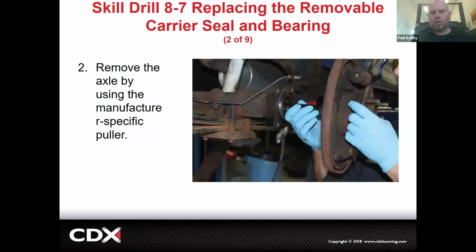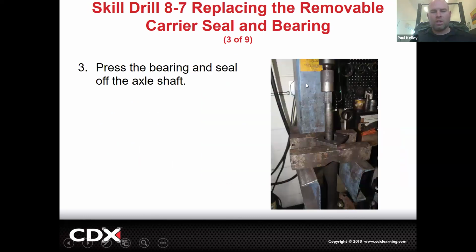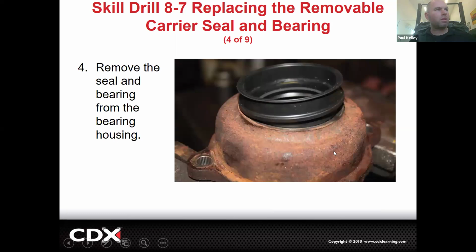Cool. So then when we go to be pulling the axles and stuff, a lot of times it'll pull, let's say that we were going to remove the carrier or do the seal. You're seeing a lot of this stuff is kind of similar. So once you get the hang of servicing these differentials, it's not a real big deal. But if we're doing this bearing, there's pressing the bearing off because it's got the splitter. This is the bearing right here.